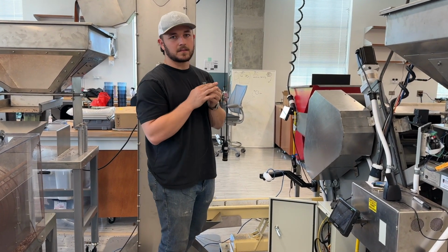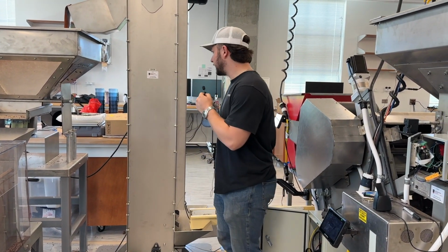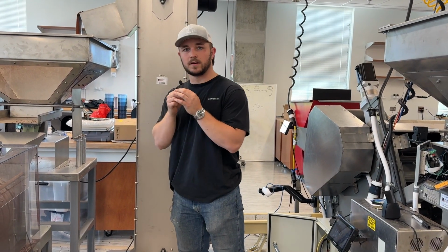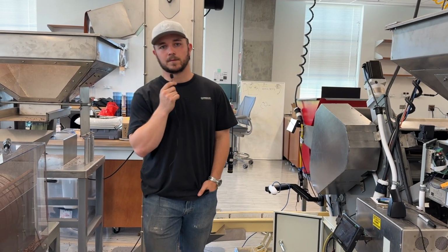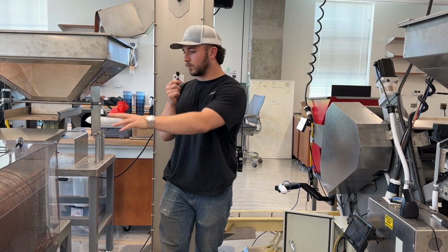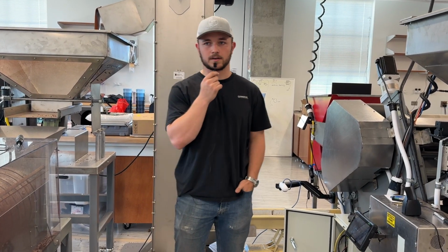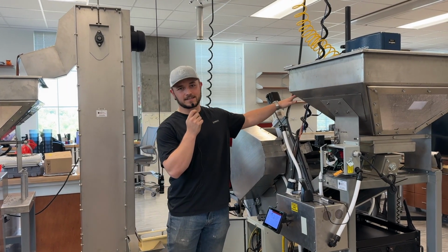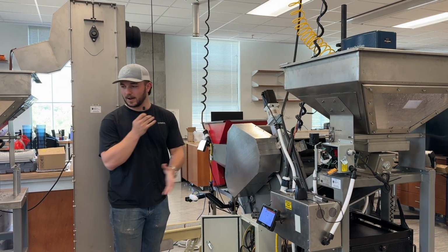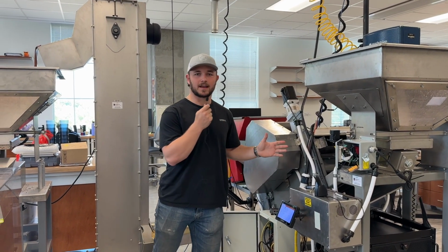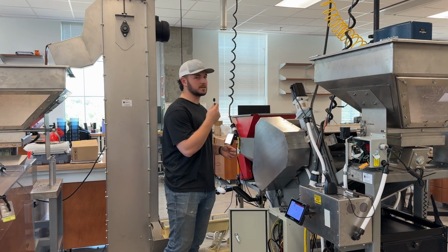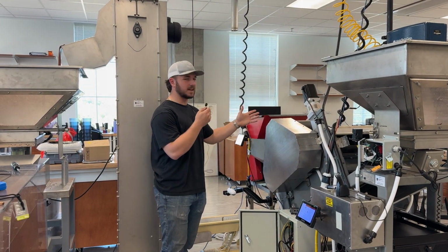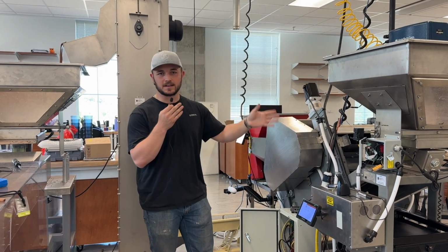And ultimately, the goal of being able to classify pecans is that it's an extra data point as we go into the sheller here that will enable us to maximize our half yield numbers once they work through the sheller and onto the blower. A point of emphasis for our project has been to work on getting precise control of this machinery. When we got most of this machinery, everything had to be adjusted by hand. Basically, it was left to the operator's opinion on where different settings, different levers and such needed to be.